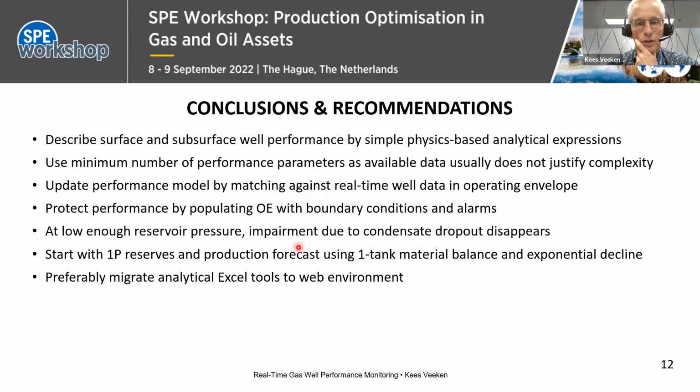And then there's just stating what we find from the two examples, that indeed at low enough reservoir pressure, at least in these two hydraulically fractured formations, where we know condensate dropout provides less impact than in a situation without fracks, in that situation it seems to disappear.